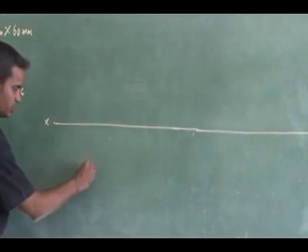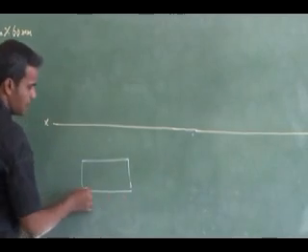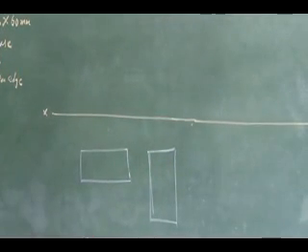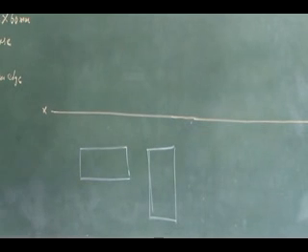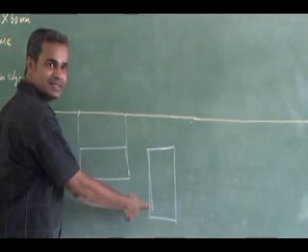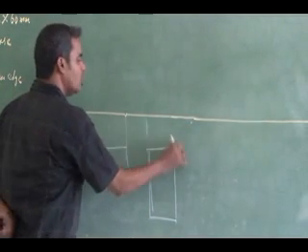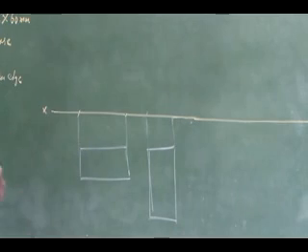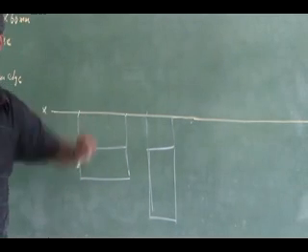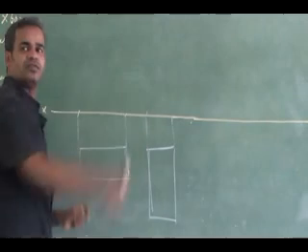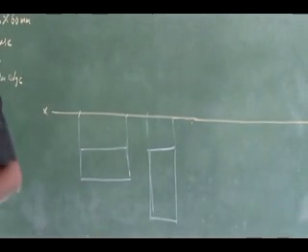And how I have to draw it? Either I can draw the same rectangle like this or like this. Which one is right? The shorter edge is resting on the ground. If I project this, which one will I have in my projection? Longer edges will be in my projection. So which one is going to be right? The first one, because I need the shorter edge to be resting on the horizontal plane. Once I tilt the front view, the shorter edge will be resting on the ground.